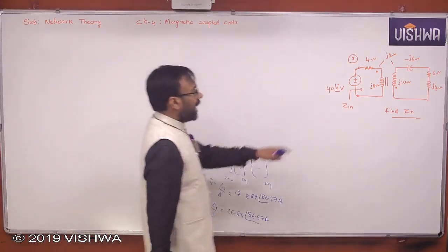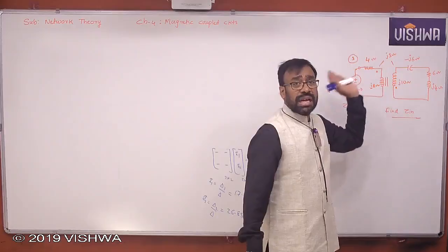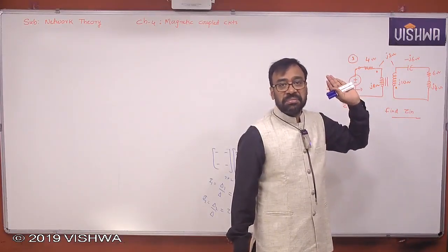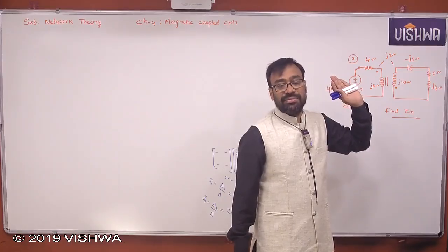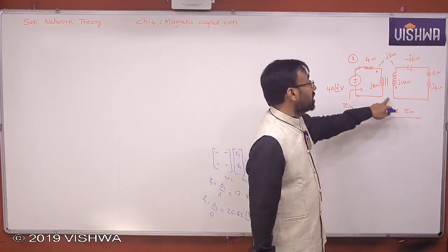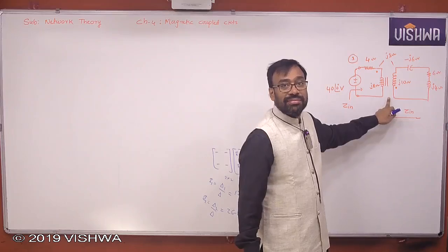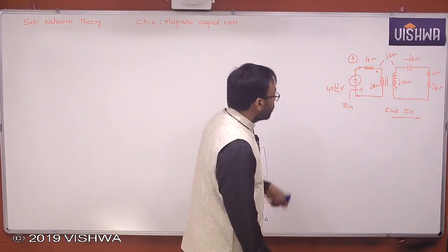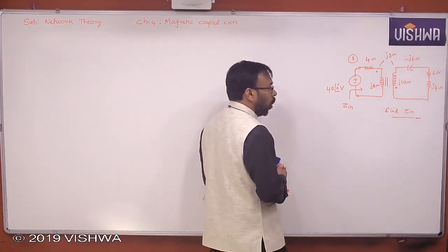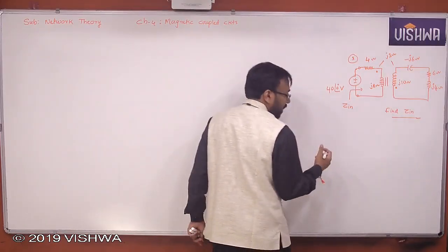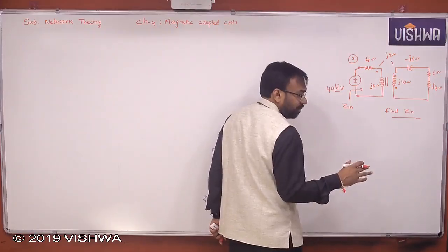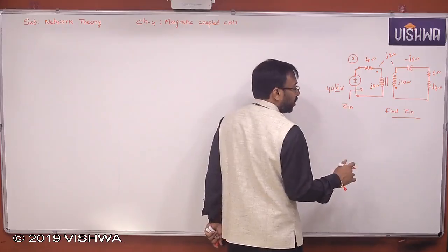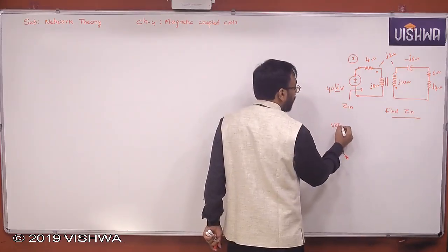So this is not an ideal transformer to convert secondary into primary. You cannot do that. It is not possible. Understand all of you? And you do not know what is the turn ratio also. So therefore, you cannot do that. But now, you can solve in a different way using ohm-amp technique. In magnetic coupled circuits, when all values are given in impedances and no ideal transformer is present, better you always apply ohm-amp method.